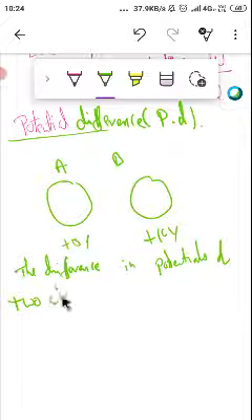Now the specific resistance units. Let me write R is equal to rho L by A ohms. Here rho, the resistivity, is equal to R A by L. R is in ohms, A is in meter square, and L is in meters. A meter cancels, so we get the units ohm meter. So the rho unit is the ohm meter. This is the SI unit. So this is about the specific resistance of the material.